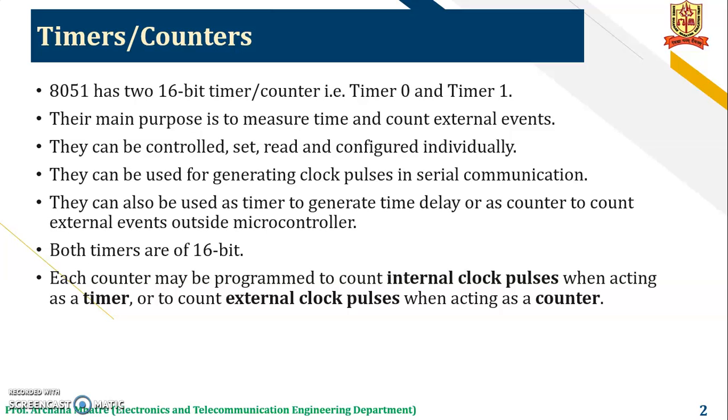outside the microcontroller. Both the timers, that is Timer 0 and Timer 1, are of 16-bit. Each counter may be programmed to count internal clock pulses when it is acting as a timer and to count external clock pulses when it is acting as a counter.